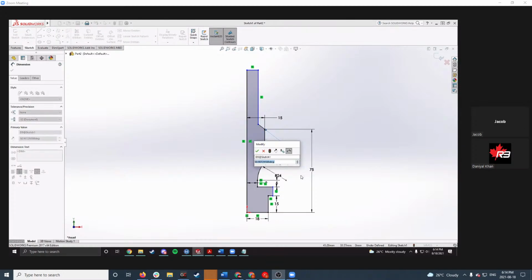So I'm just going to click. Instead of typing in a number, I'm going to type in equals A, and then it's going to have this globe symbol come up, and I'm just going to hit enter. Oops, I selected that arc sign by accident. So equals A, enter, and it's going to prompt me to create a new global variable named A. I'm going to click yes.